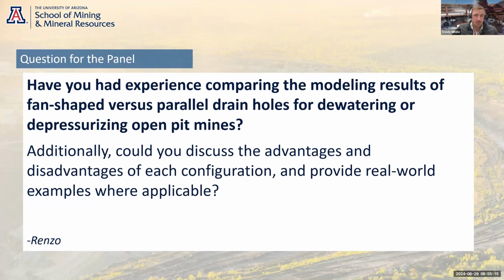Yeah, so just to add, at 2 of our operations, we actually had to go with a third configuration, which were vertical and sub-vertical wells or bores drilled from the pit crest and sometimes in the pit, purely because there wasn't access to the face to drill the horizontal drain. So you can also implement vertical and sub-vertical wells, though you obviously then have to pump the water out of those. But in these 2 examples, that actually worked out more cost effective because the drilling was significantly cheaper, and we were able to deploy some relatively low cost pumping solutions as well.